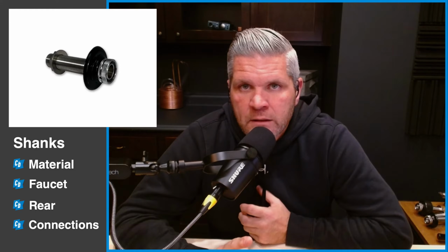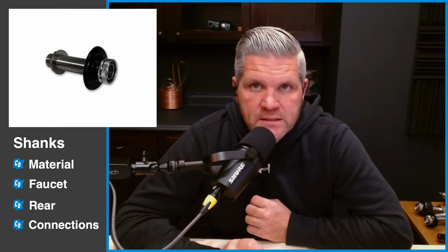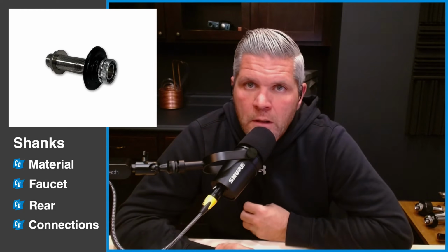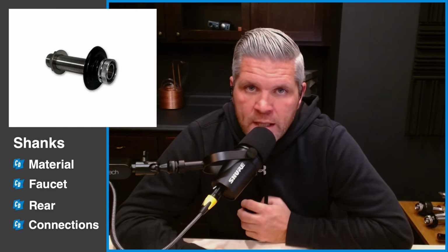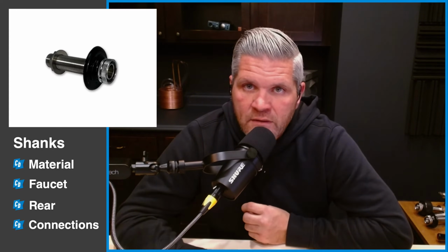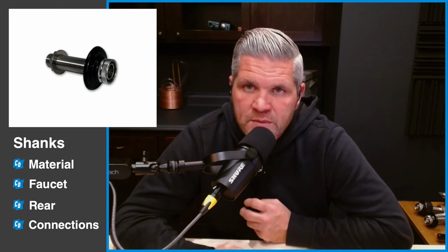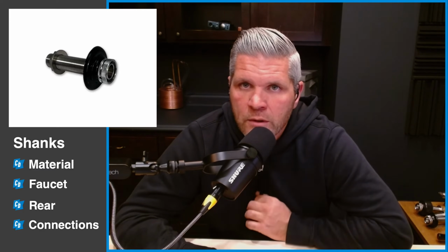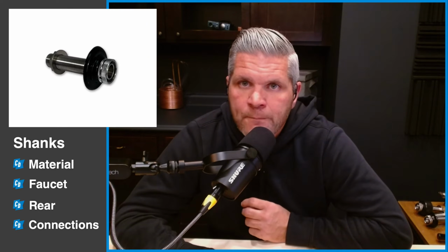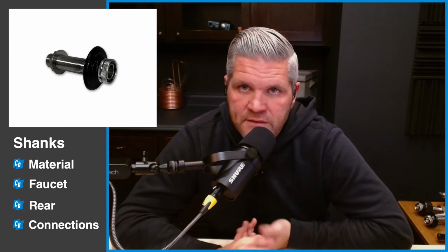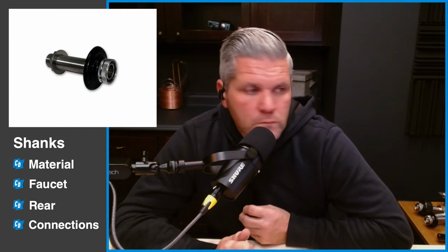There are 2 types. You're going to find either stainless steel or chrome-plated brass. The chrome-plated brass shanks are a lot cheaper, especially if you're on a budget. But what happens is that chrome plating eventually wears off, because beer, wine, anything you're going to pour out of there will be acidic, and it eventually eats away at it. And as soon as the brass is exposed, it creates a metallic, weird flavor. So you don't want that anywhere near your beer. And it's really porous, so it's really hard to get clean. So bacteria is going to wind up in your shanks, and it's going to be really difficult to get rid of it. So buy quality components.